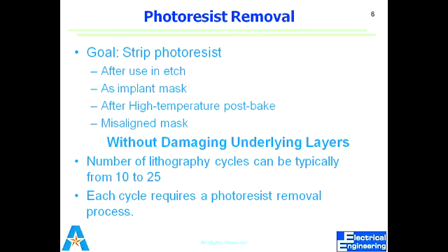So what I'll do, I will expose these areas that I need to remove. This is my photoresist. Then I go for etching. Etching will remove the thin layer that is exposed, and at the end I remove my photoresist. So the same pattern can be achieved in both ways.